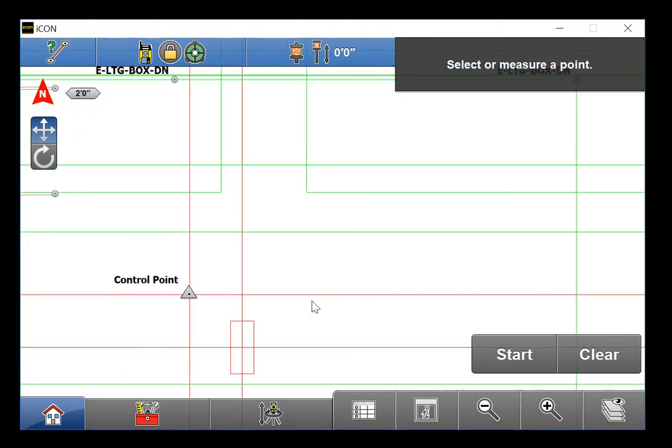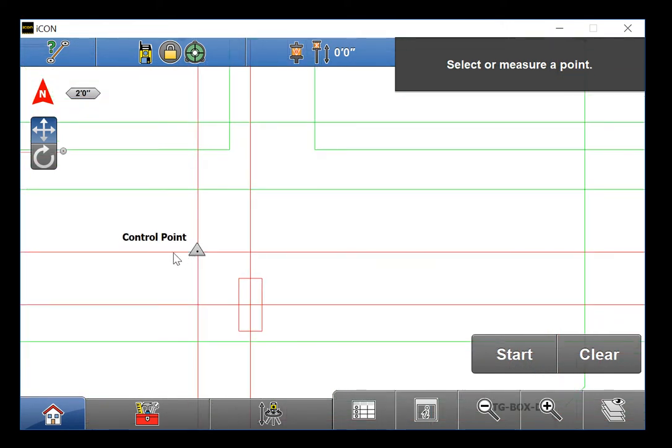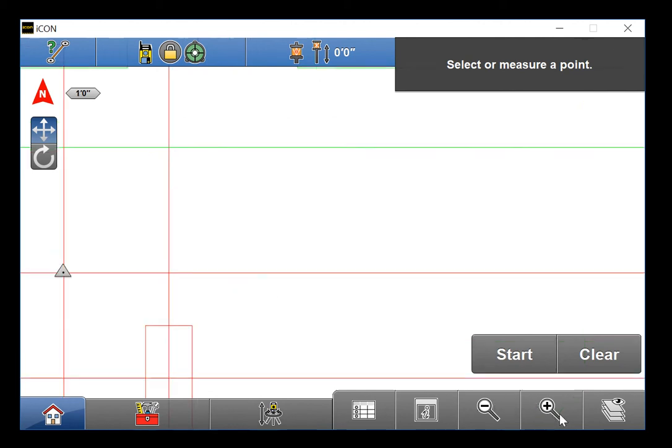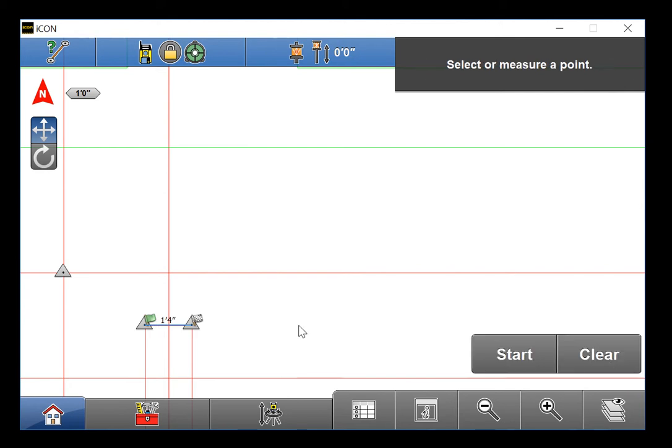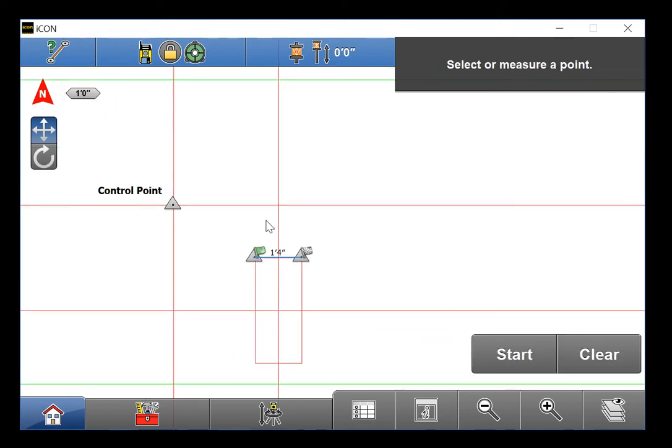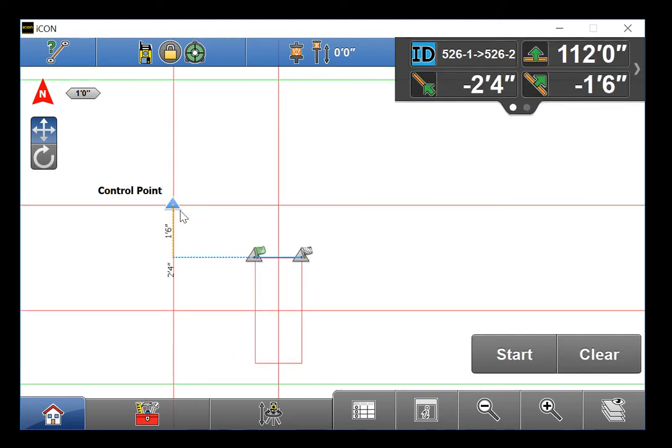Another situation is you want to check to make sure the control lines on the deck are accurate. One of the quickest and easiest methods to do that is to take your tape measure and measure from the face of a column to the control line and make sure that dimension is accurate. Many times this will resolve discrepancies in control lines automatically.